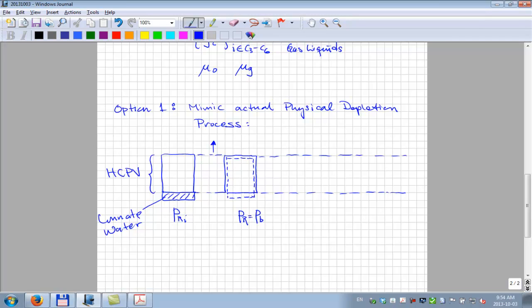So now you've got this water that's expanding. If it was a pure water, it would just expand on the pressure reduction. But now it's losing mass, because that water is actually saturated with components in the oil. But what you find in Chapter 9 is that, in fact, the expansion due to compressibility will win over the loss of mass. So the water volume will actually expand.